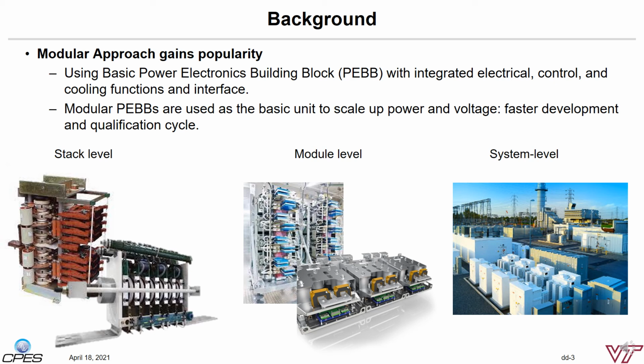This also reduces the development risks when using high switching frequency semiconductor devices like silicon carbide MOSFETs. The modular approach can dive down to the stack level, which is the integration of the semiconductor devices, monitoring, and gate driving units into a higher power and higher voltage switching unit, or to the subsystem level like MMC submodules, and all the way to system level like paralleling drives for higher power motors.